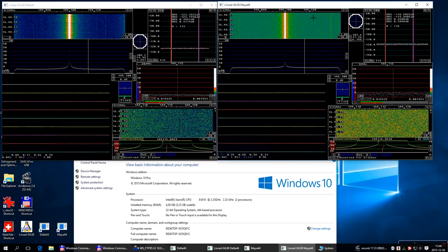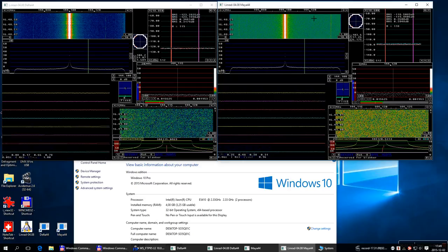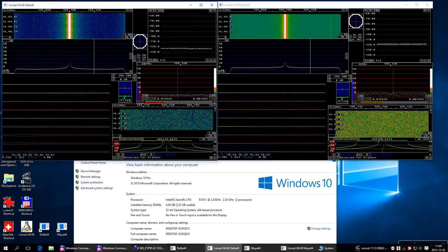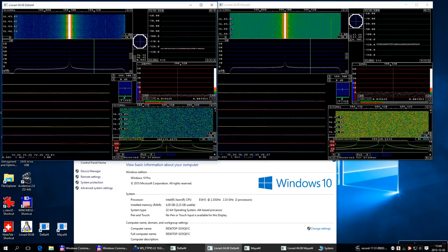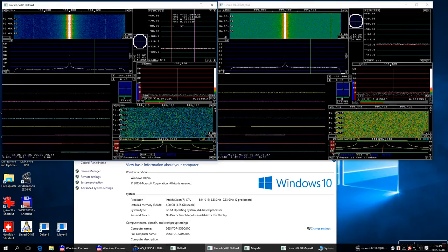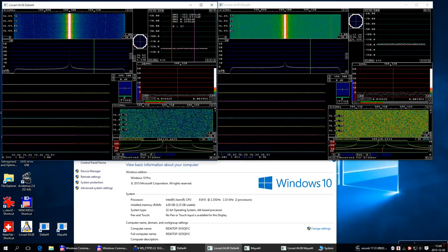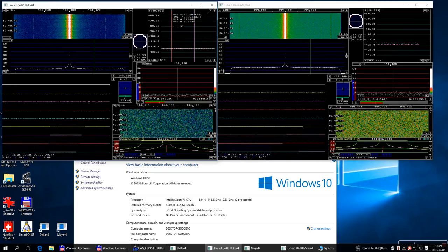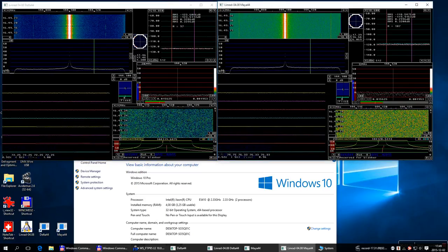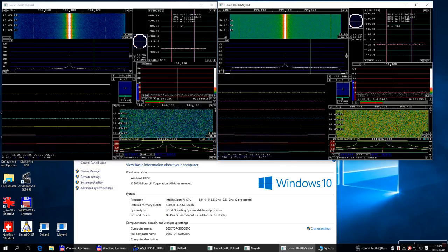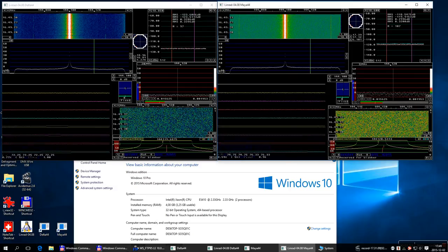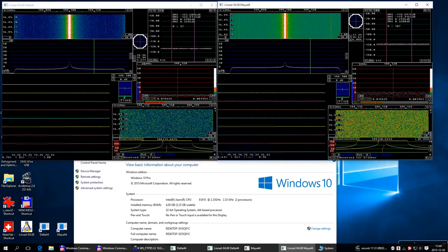If I step up to 120 here and here, and then wait for a while for the new value to come on the S-meter graph, the noise floor on the Delta44 is minus 123.5, and on the Maya it is, well, it didn't change noticeably. So this is the situation we had.